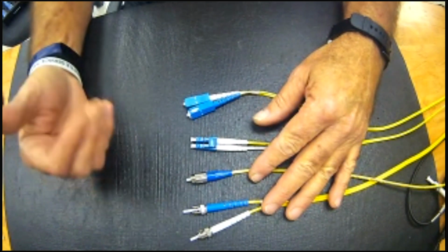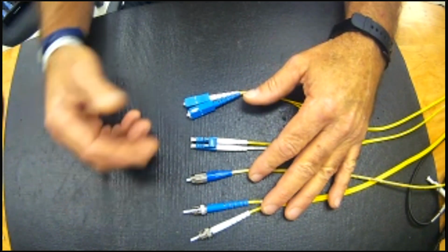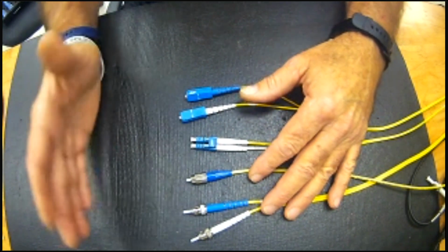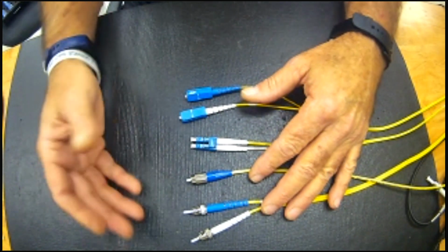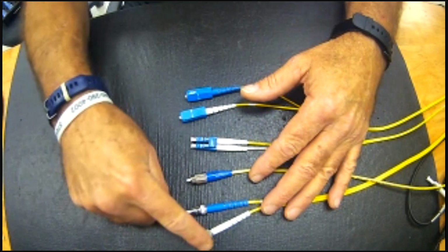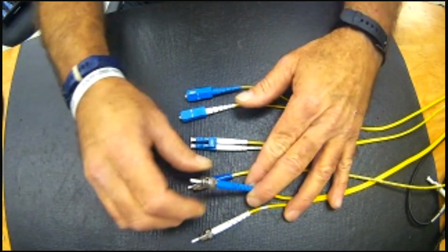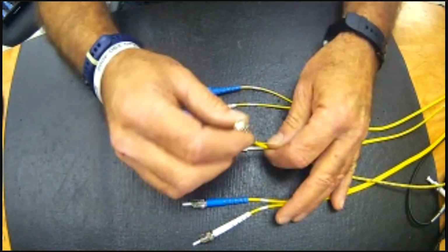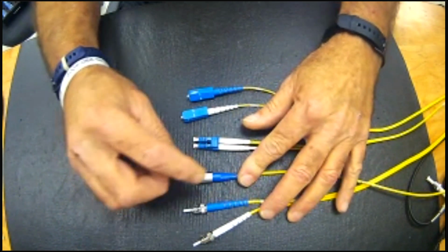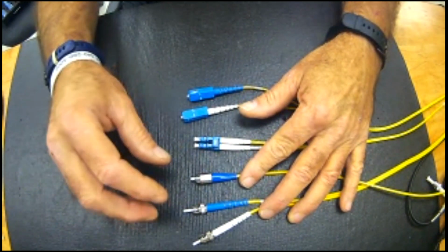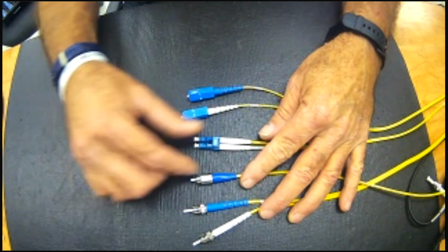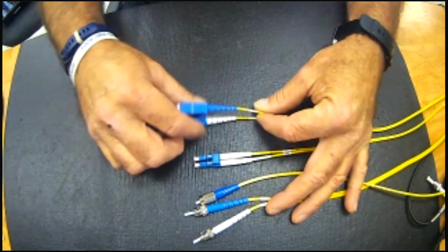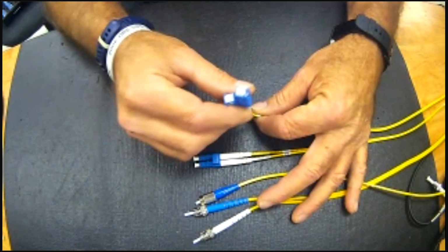Well, the reason we say that is we say everything phonetically, because I've shipped hundreds of patch cords to people for them to turn around and go, that's not what I want. So I insist that you give it to me phonetically. Sam Tom, which is the most common bayonet locking field connector. Frank Charlie, which is an FC, which is a threaded connector. You'll only see this with like satellite uplink, downlink, and RF transceivers. Lima Charlie, the LC, and Sam Charlie, its big brother.